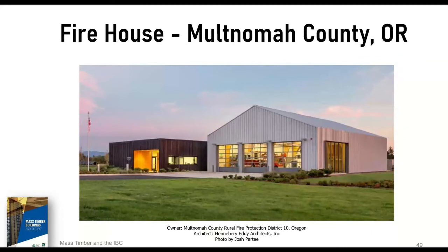Now, stepping down in scale. The use of mass timber elements in tall structures here in the U.S. has essentially lagged the rest of the world. Limited by the heavy timber or Type 4 type of construction within the IBC, the building code limitations up to the 2018 IBC limit the heights and stories to those below the high-rise thresholds.